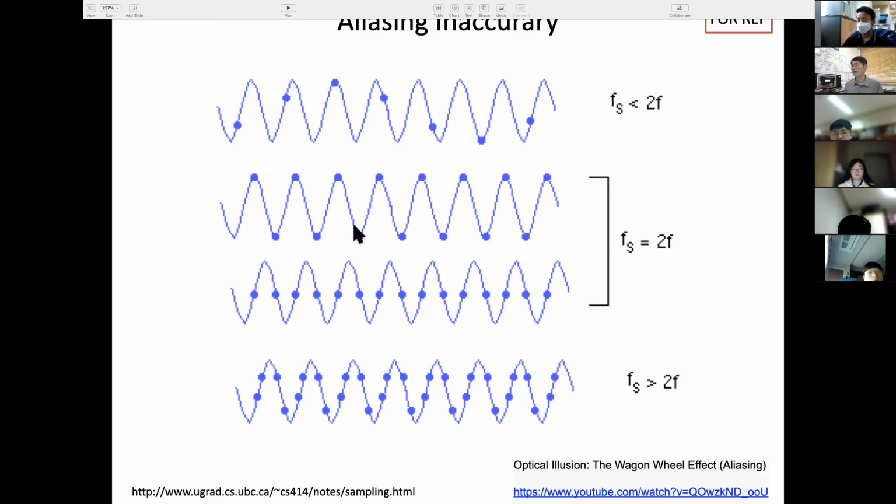If you happen to match the phase with the top and bottom, during this one period you collect the signal 1 time, 2 times. And if you happen to meet the top and bottom, then you know the sampled signal has the same frequency. Which is great, okay? What's the problem with this?